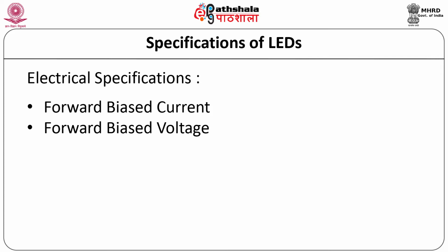It is necessary to ensure that the maximum current rating is not exceeded. This could give rise to excessive heat dissipation within the LED chip itself, which could result in reduced light output and reduced operating lifetime. Reverse voltage. An LED is not tolerant to large reverse voltages. They should never be run above their stated maximum reverse voltage, which is normally quite small.